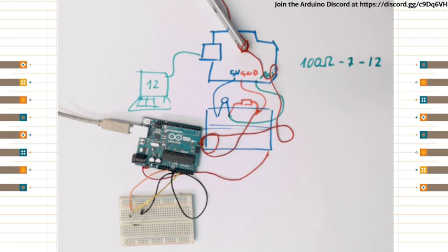The room here probably will have 20 something degrees. When I touch it, the temperature should rise up to like 30, 32 degrees more or less. It's always a little bit less than the 36 that we should be at, especially because I have no fever today. But for that difference of 10 degrees, I only get between 7 and 12. So it's not a really good reading.